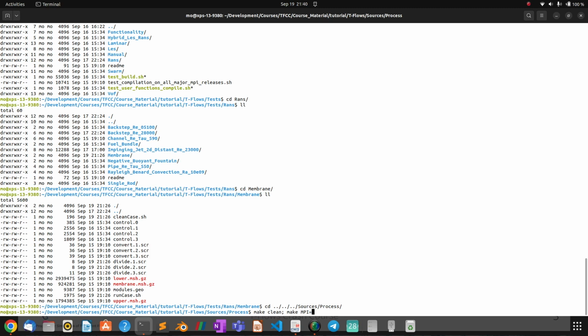For running the problem in parallel mode, we have to put this command, as we learned before, mpi yes, which gives you the option to run mpirun before your process. And one last thing is the case directory, which we need to specify to make sure that if there is any user mod function, it's hooked up to the process while running the problem.